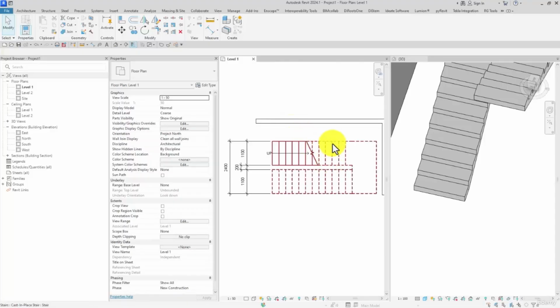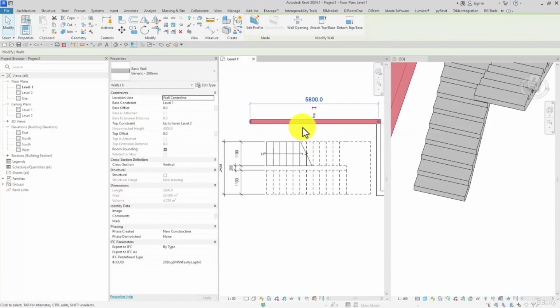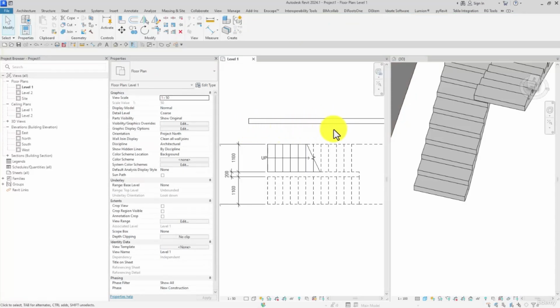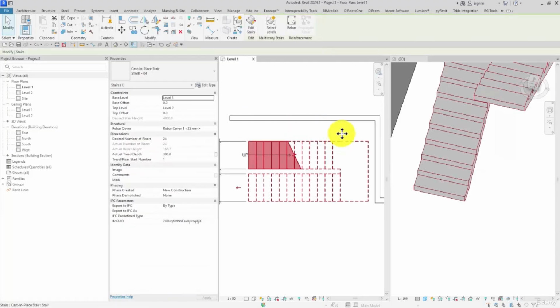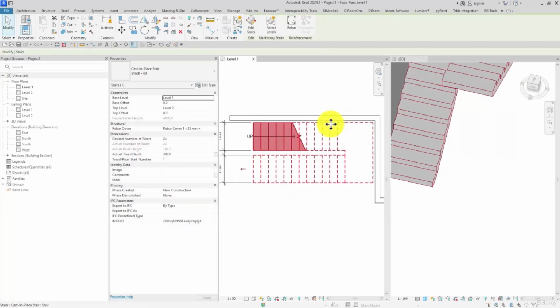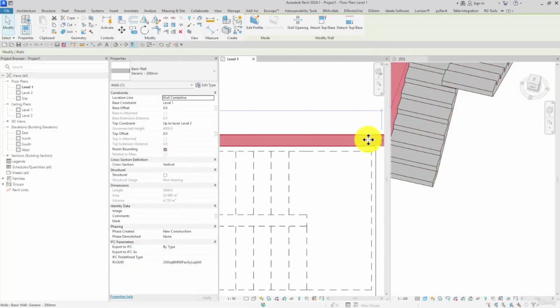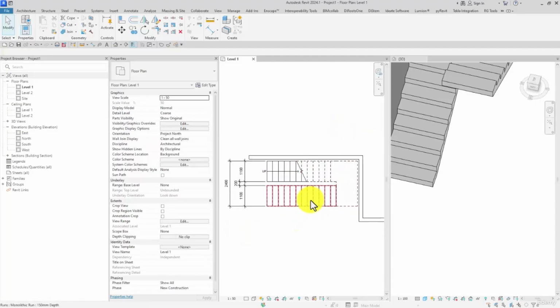And note that while we are working with Revit, this distance or width is the space occupied by the stairs. However, in the continuation we're going to add the finish layer to the walls. If we do not consider the thickness of the finish layer, the wall should be joined with the column, and then we add the finish layer to the wall, and 2 meters and 40 for the stairs.